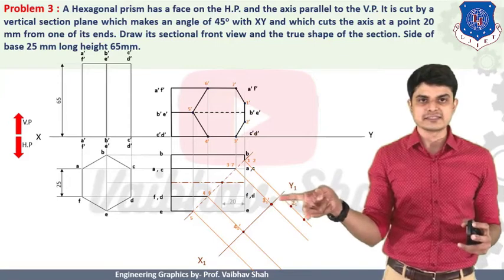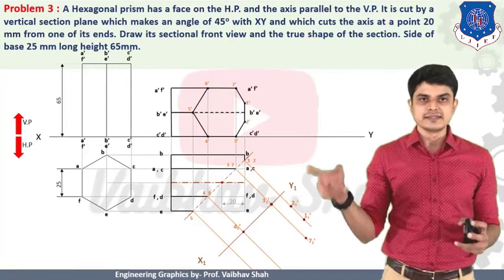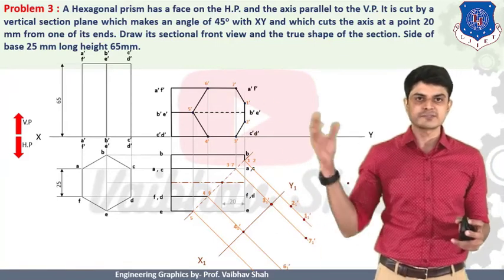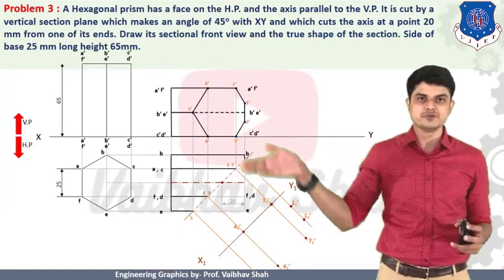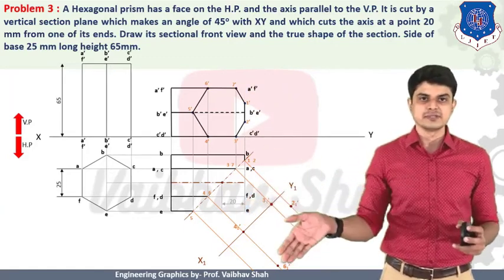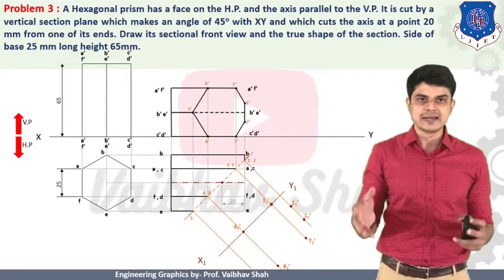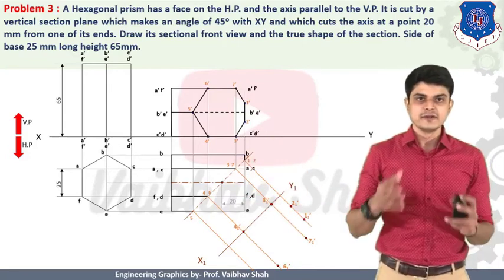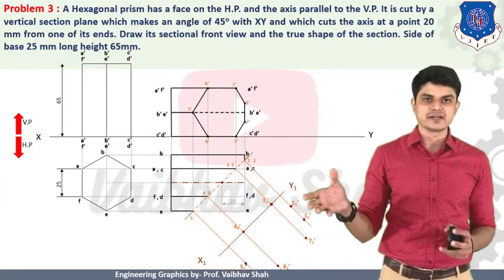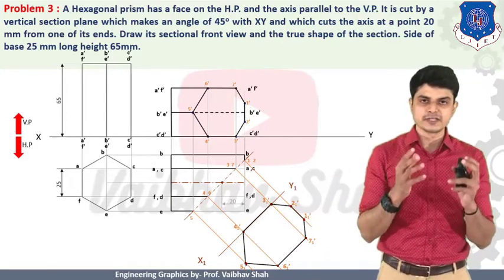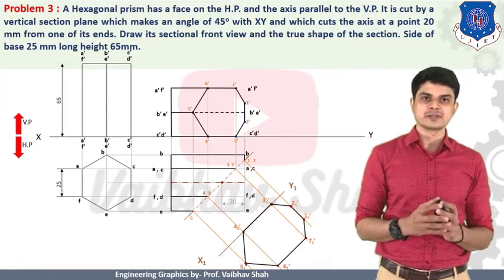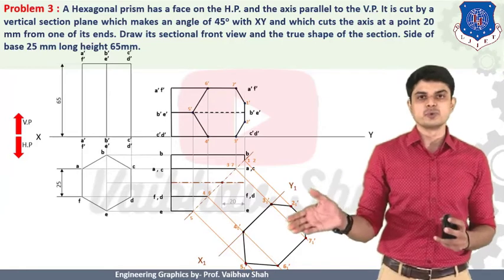You will be having point 7 like this from this xy line. Then you should take each of the points from the respective xy line above this xy line, and you should put the dimension just below this xy line onto your perpendicular lines on the respective point. So you will be having this final point generated like this. And after having these points, you should connect these points by a dark smooth line. This is nothing but your true shape.